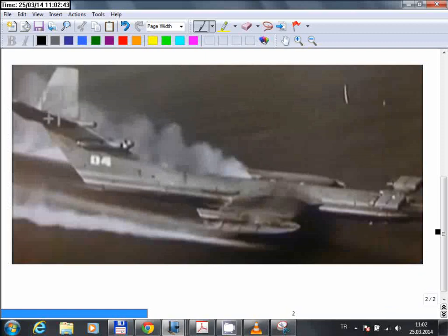So if you look at its wings, the aspect ratio is quite low. From what we know, if you try to fly this airplane high in the atmosphere, you would get very bad performance because of this low aspect ratio wing. It's rectangular and the aspect ratio is really low. Normally, if you try to fly this up in the air, due to these vortices, you would get a lot of increased drag. But since it's flying close to the ground, you don't get that bad aerodynamic performance, and that's how it becomes very efficient.